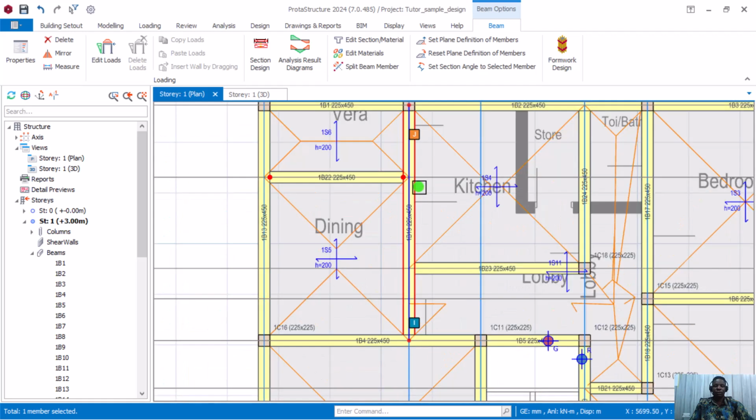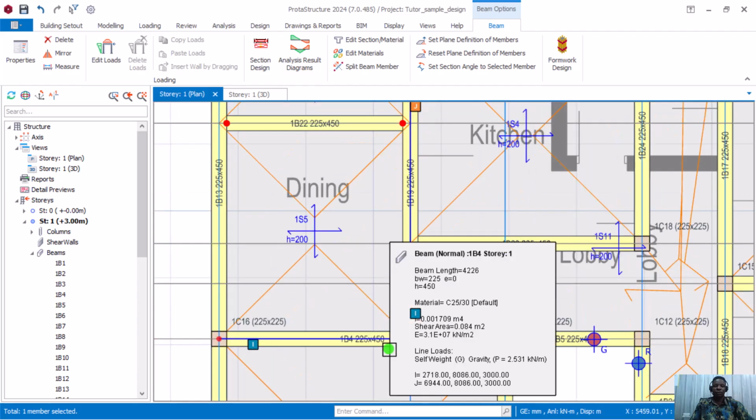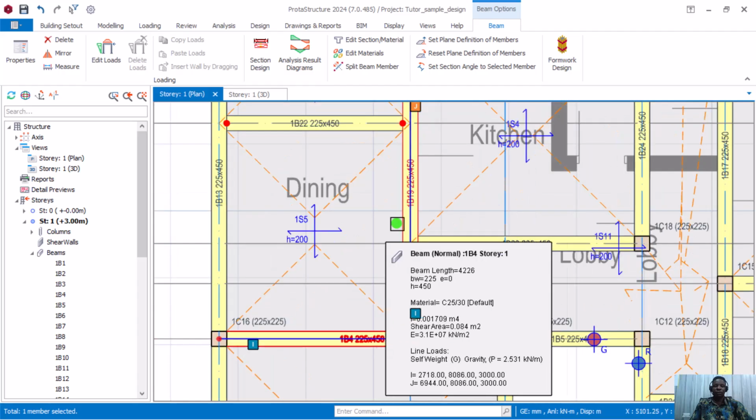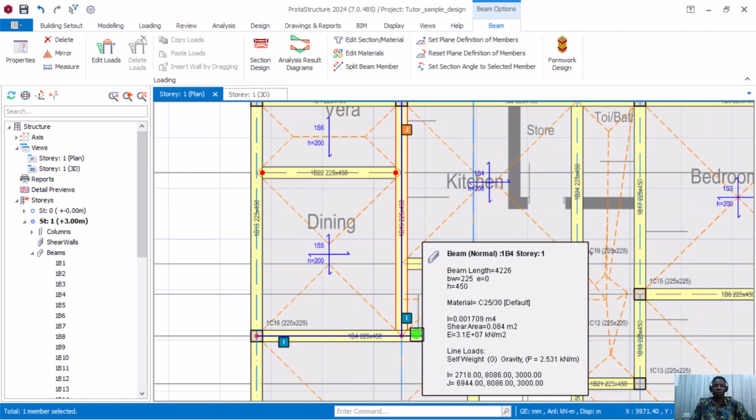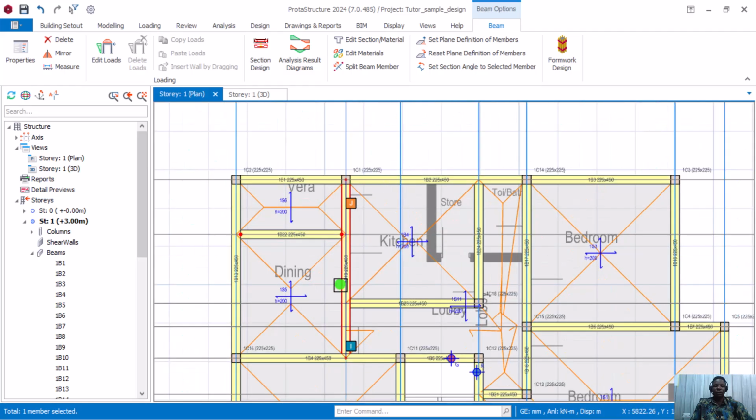So in the same thing over here, you can see the force at this end, this beam is now going to be supported along this beam. So this is now going to be another primary beam, and this will now be a secondary beam to this particular beam. All right. So this beam is now going to be taking care of all the stress coming from this beam as distributed. So I just have to throw in that analysis so that you understand what I'm doing here.